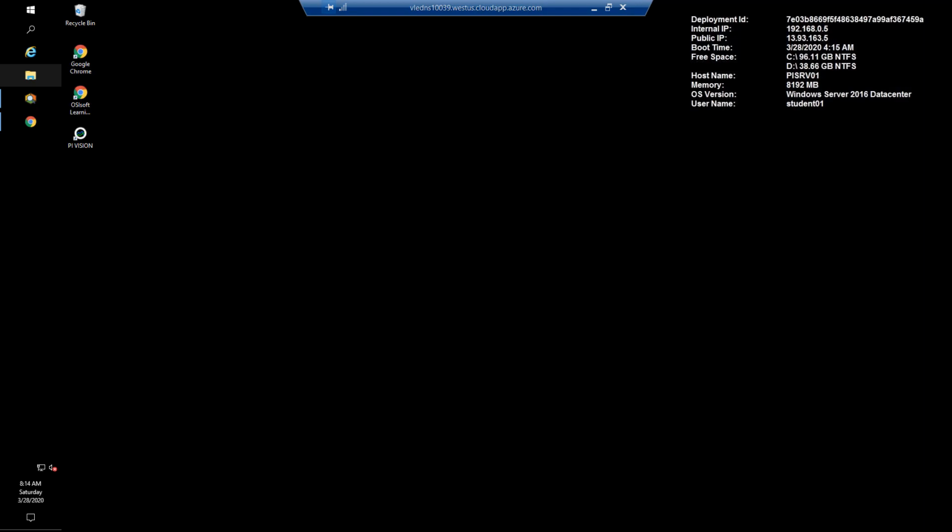The third issue was that we had the incorrect units of measure applied to our sealer temperature. So we went ahead and told Asset Framework that the data coming in was in Celsius and needed to be displayed in Fahrenheit. The fourth issue is the one that saved us the most time going forward, where we used parameterized queries in our Asset Framework table, and we moved from importing 300,000 rows, and we now only import the rows that actually get queried.